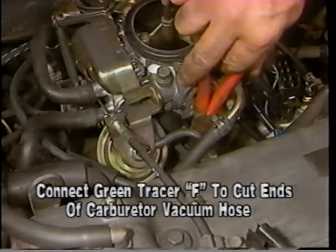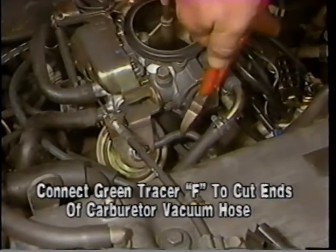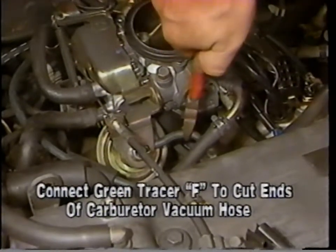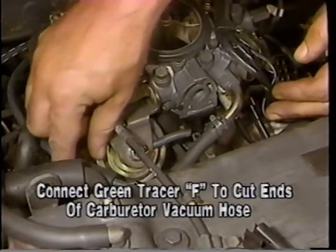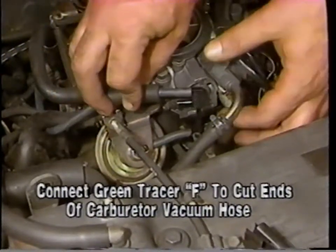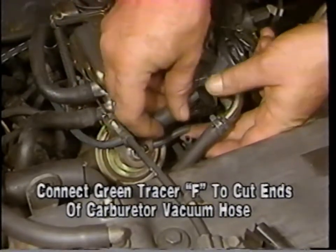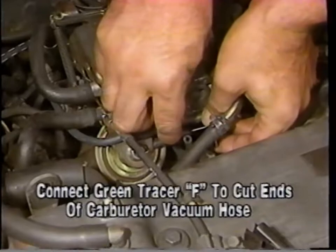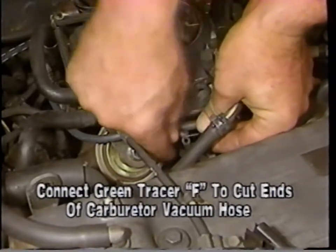Next, locate the vacuum hose between the carburetor base and depression chamber and cut the hose as shown here. Route the harness vacuum line with the green tracer and F connector around the carburetor and connect the cut ends of the hose to the F connector.